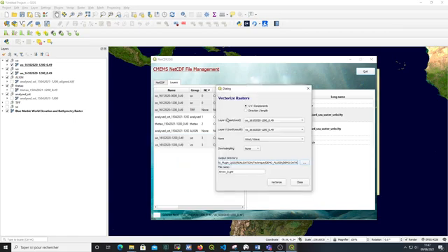Here you have several options. You can select the UV components because we are using a component for the eastward velocity and a component for the northward velocity. Load the layers corresponding to your components, and here we can change the norm because the norm is not the same for currents and for wind and waves, so we are selecting currents.